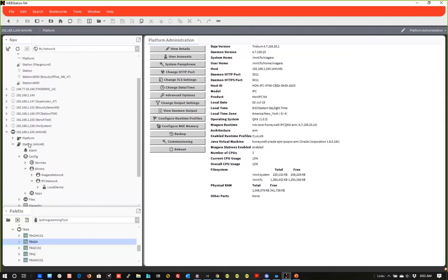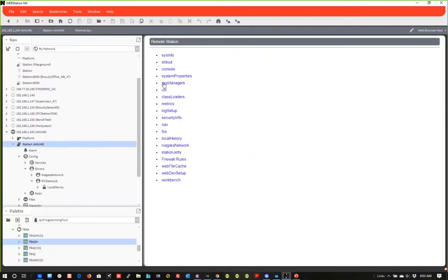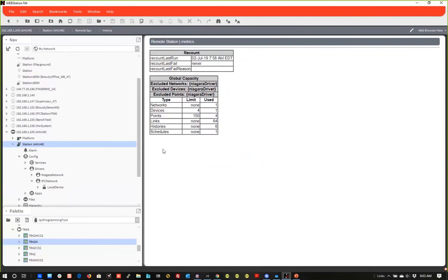Hey, Frank, the modules, are we able to use, like, AX community modules or the Honeywell CL modules? Is it open to all third-party modules, or are we limited in any way? It's standard Niagara, so that shouldn't be an issue. CL's not a standard Niagara module, so I doubt that'll work, because that's got to have a special license to be able to work with the CL stuff. So no, I don't expect the CL modules to work with this.